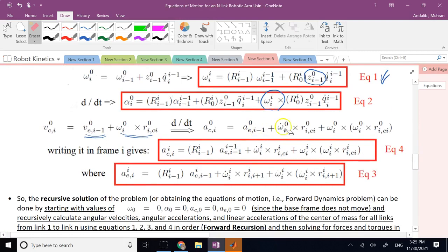And this is what you can see, that the acceleration of the centroid is again the acceleration of the left node, right, in that picture, plus the tangential term alpha cross I plus the normal or centripetal term. And instead of writing everything in the inertial frame, we can write everything in the body attached frame.